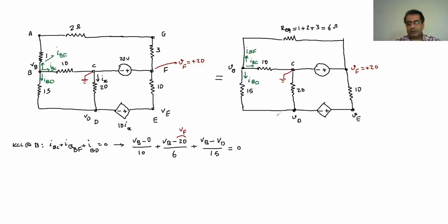And then the problem is that these two are connected to the battery. So if I want to write the KCL at this node, because it's connected to the battery, it's not going to give me anything because I don't know the resistance of the battery. So one thing I have to do is, either like here, we put a reference at one end of the battery, which we already do. So we already put the reference at one end of the battery. The other option is that I have to take these as, I would say, the super node.